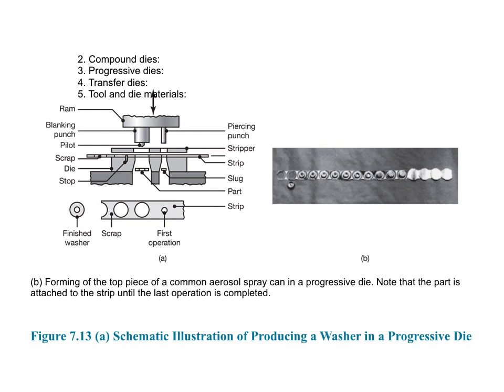Next are compound dies. Several operations are performed with one compound die. They have higher productivity. However, you can only obtain relatively simple shearing with this process. These dies are slower and more expensive than individual dies.